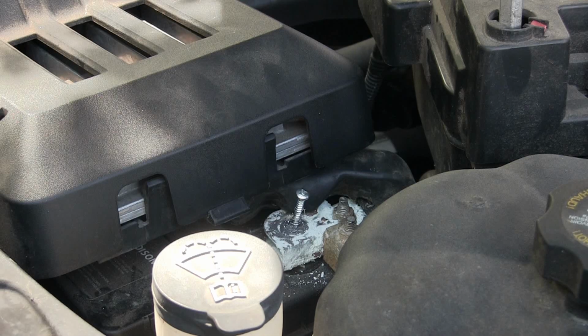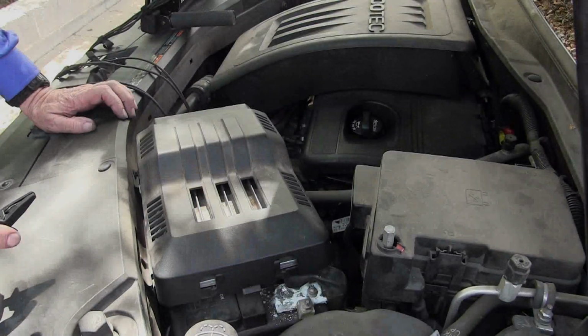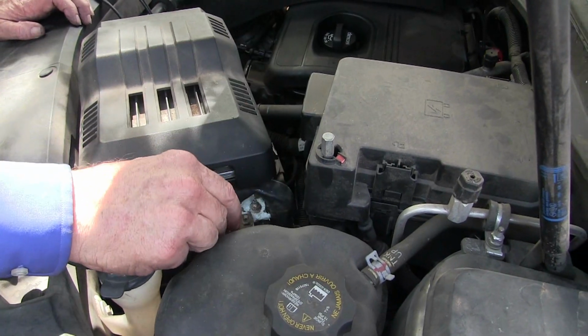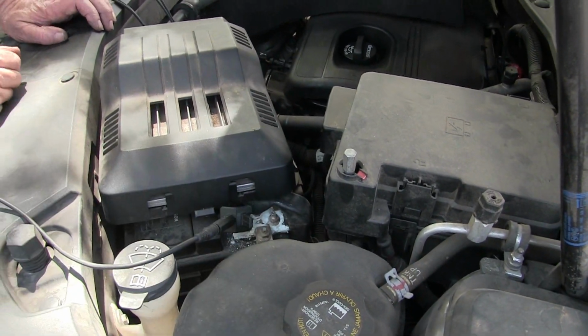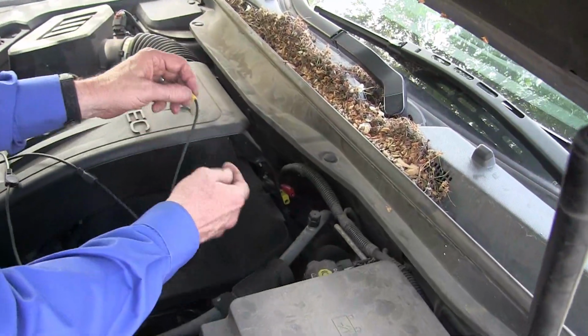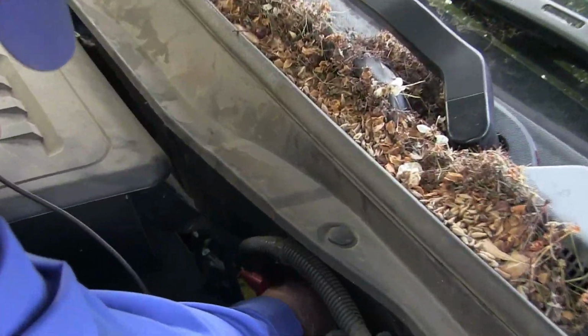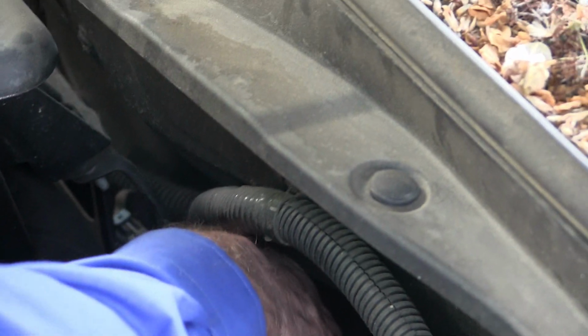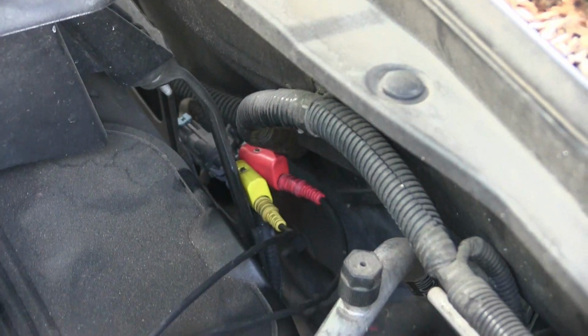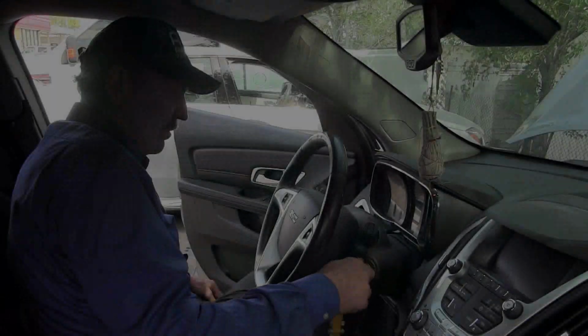So there we go, we've got the screw in now. Now that we got the screw directly into the battery post, we're going to go ahead and connect to the screw. That gives us a good ground plane with the oscilloscope. We're going to now take channel 1 and channel 2, and we're going to get into the front O2 sensor's output, and the redundant ground. Let's go ahead and look at those signals now.